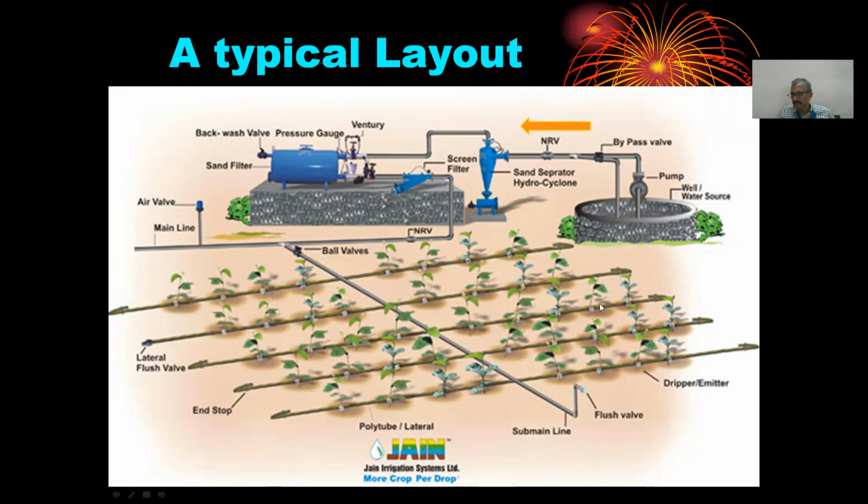then after water comes out, this air valve will not have any kind of connection to this submain. So in that way, this air valve will help functioning only for the main pipe alone. So if one provides an air valve after the ball valve, then it is better.